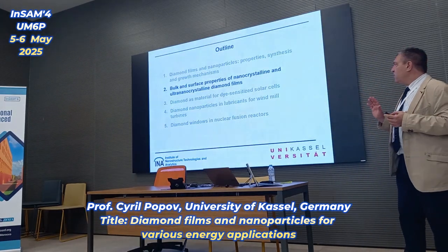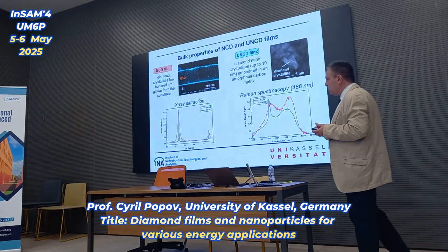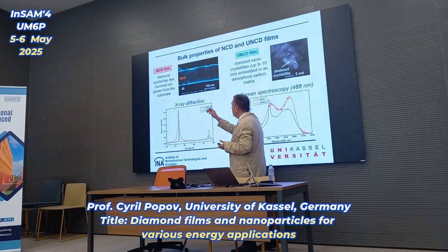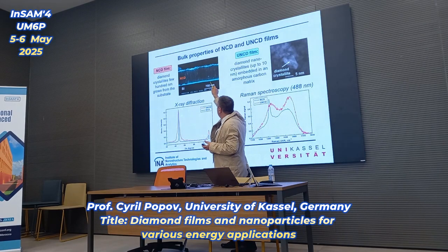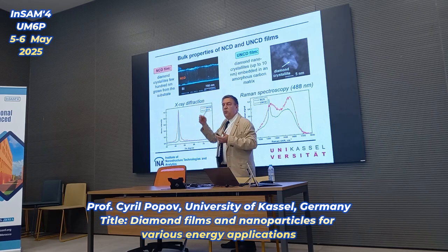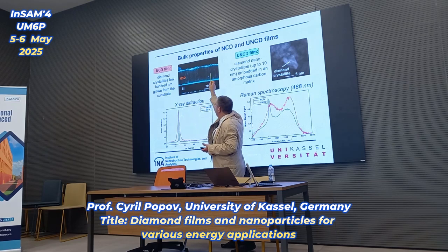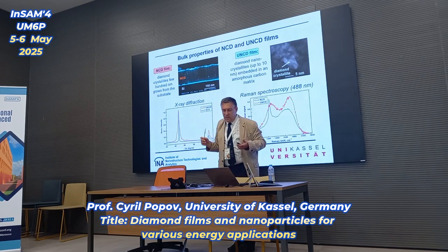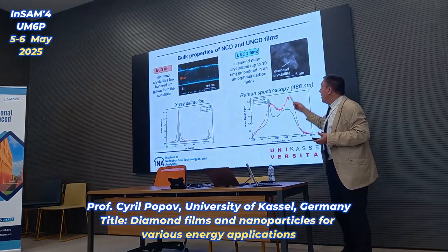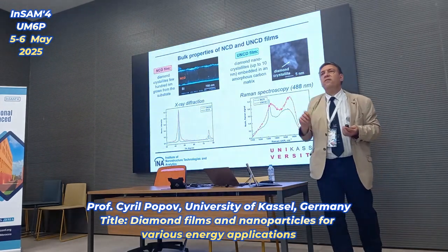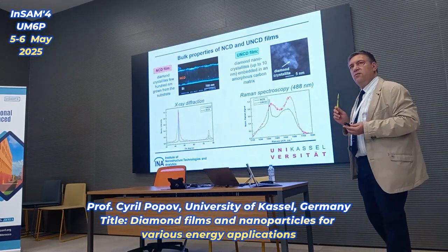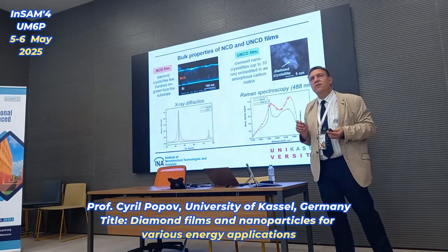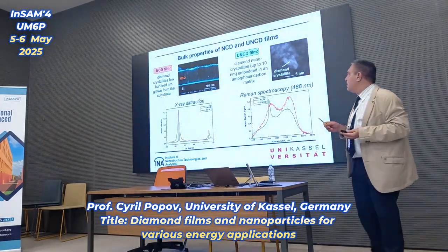So, about the properties, to be able to differentiate the properties of the nanocrystalline and ultra-nanocrystalline diamond film. The nanocrystalline diamond films, the crystallites, as I said, of several hundred nanometers, they start the growth from the interface, from the nuclei created during the pretreatment upwards. The longer we deposit, the thicker the film, and the higher or larger the crystals. By the ultra-nanocrystalline diamond film, we have extremely high secondary nucleation rate. It means we interrupt the growth of diamond and start the growth of new diamond grain.